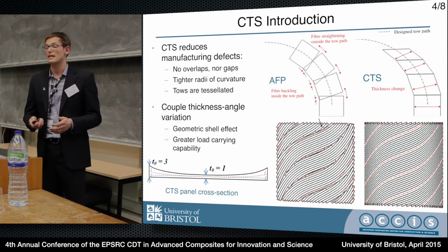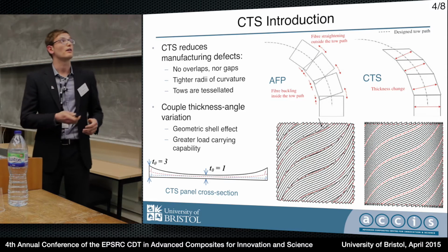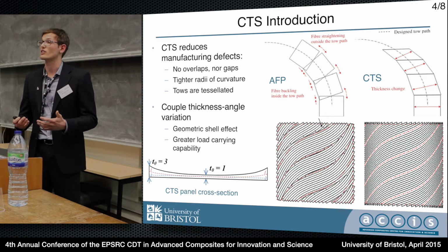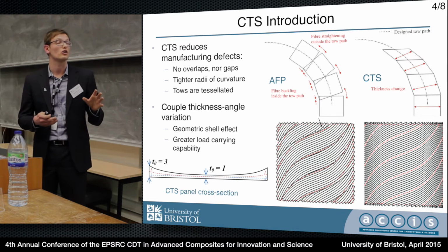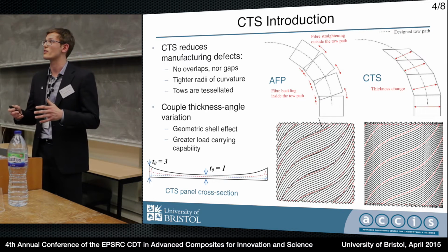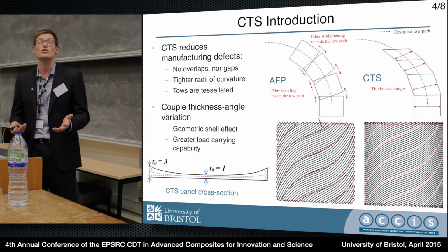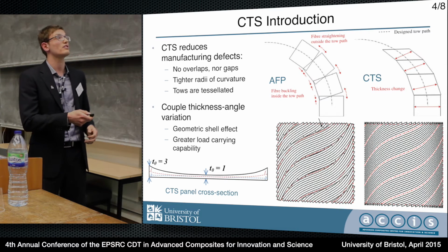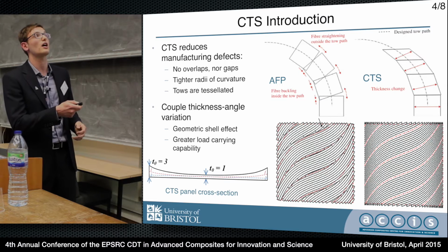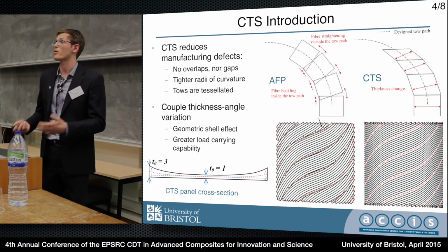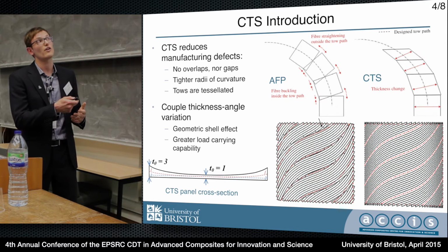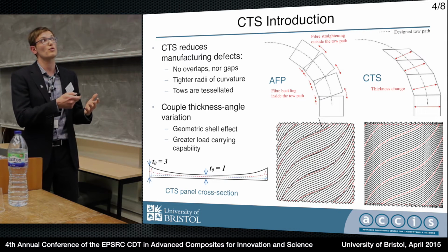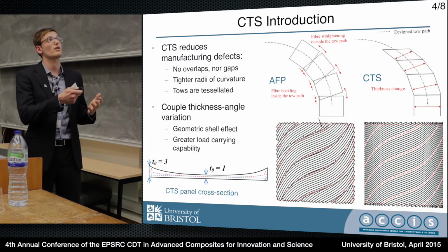Another possibility that the manufacturing techniques open up is that we can facilitate smooth transitions between areas with different layout requirements. For example, in trees, there's a smooth transition of the fibers from the trunk leading into the branch, and we could apply this concept, for example, to have fibers smoothly transition from a fuselage straight into a wing.